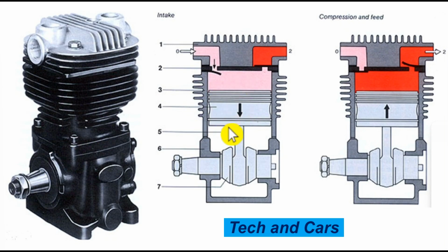Now, when the piston is reciprocating up and down inside the cylinder, it will either generate vacuum or cause pressure to exist. When you look at the main principle of operation, when the piston is moving from TDC down to BDC, on this stroke you can see the intake flap is open. This right here is the intake passage. Air from an air filter will be supplied to this cylinder, and the downward travel of the piston will cause vacuum inside this cylinder. That partial vacuum will open the inlet passage and fresh air will be admitted to this chamber.